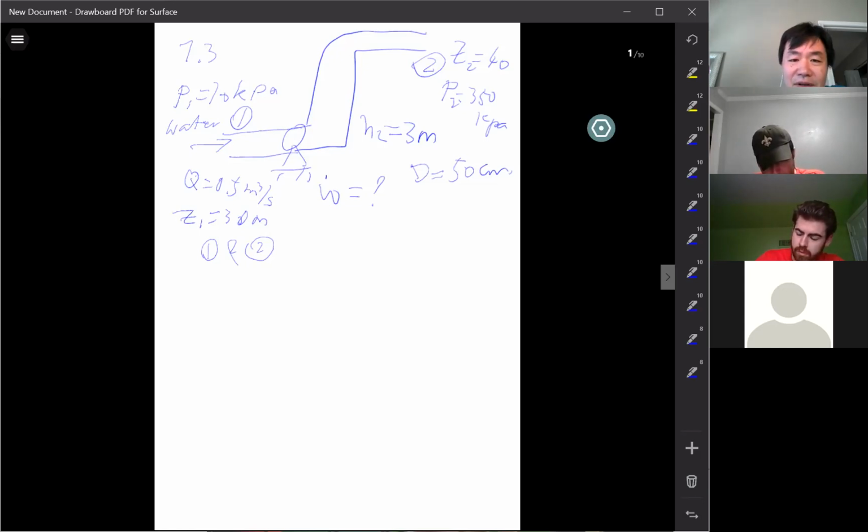Now, you need to calculate the velocity. Go ahead, calculate the velocity for me. I think the only thing in the equation you probably don't know is the velocity, right? Water, gamma is 9,800, easy. In the calculation, be careful. Pressure, don't use 70 kPa, use 70,000 Pascal in the calculation, okay? But now, calculate the velocity first. You have the flow rate, right? You have the diameter. Can you calculate the velocity value?